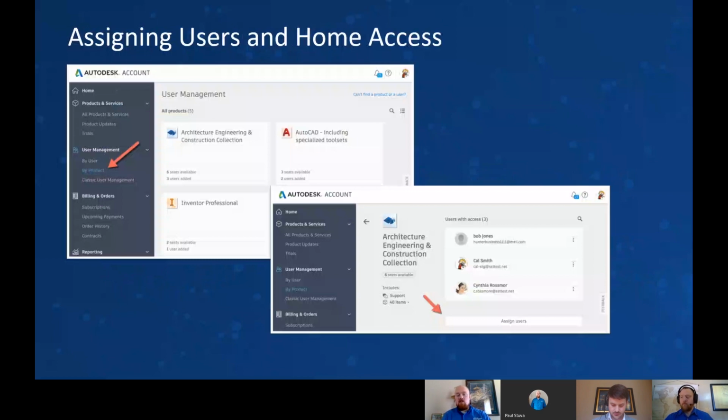So as Ian had mentioned, you can get a BIM 360 trial, and it is extended to that May 31st date. It is important to note that that trial should be started by a project or account admin, somebody who is going to be a member of the team that is going to be assigning and managing project access. If you have everybody run out and start a trial on their own, you're going to create a disparate set of users all on different sites, and they're not going to be connected. So you want to make sure that you have one person designated as a team lead for it. Create that trial, start getting your project set up.